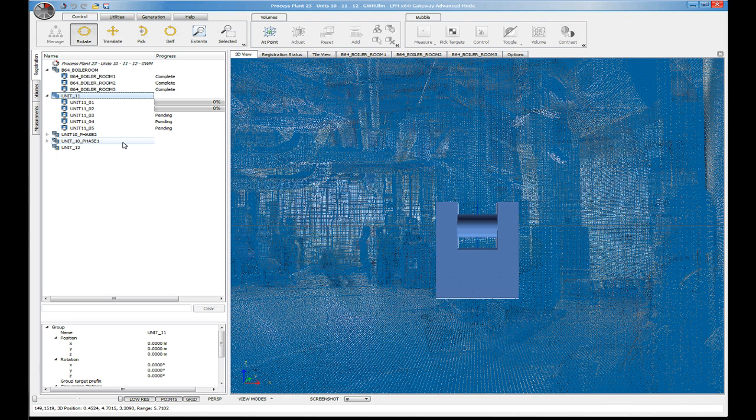For those of you who are familiar with the old LFM register, you will know that we can identify common points between the scans to use as targets, for example, marks on walls or corners of signs. Whilst these tools are still available in LFM Server 4.2 Gateway mode, today we will be showing the new scan manipulation tool. This allows us to drag the scans into roughly the correct position and then reposition using LFM's intercloud registration algorithm.